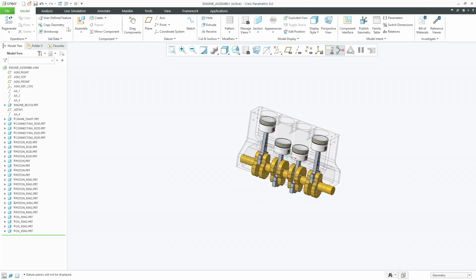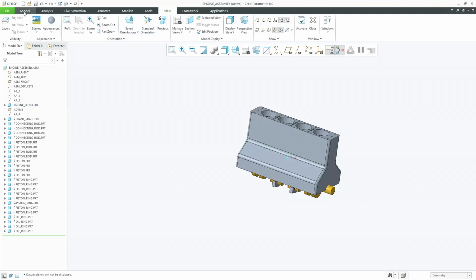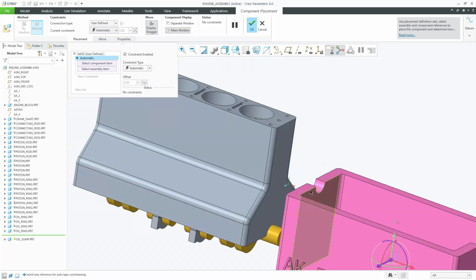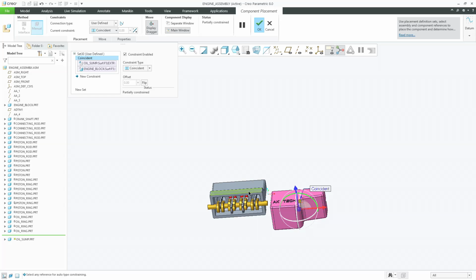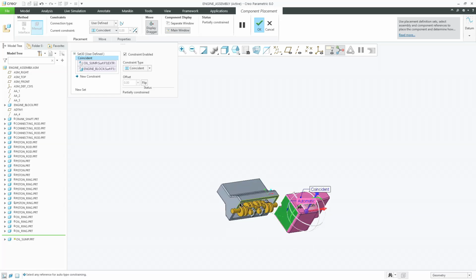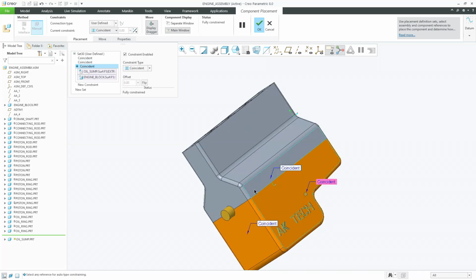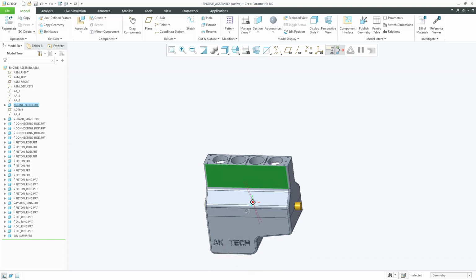So to get the oil sump, I'm going to make the engine an aluminum body, and I'm going to bring the oil sump here. So for the oil sump also I'm having a rigid connection. Why? It doesn't have any mechanism in that. So I just make coincidence directly on the surface to surface with the engine block, and there is a provision for the crankshaft output.